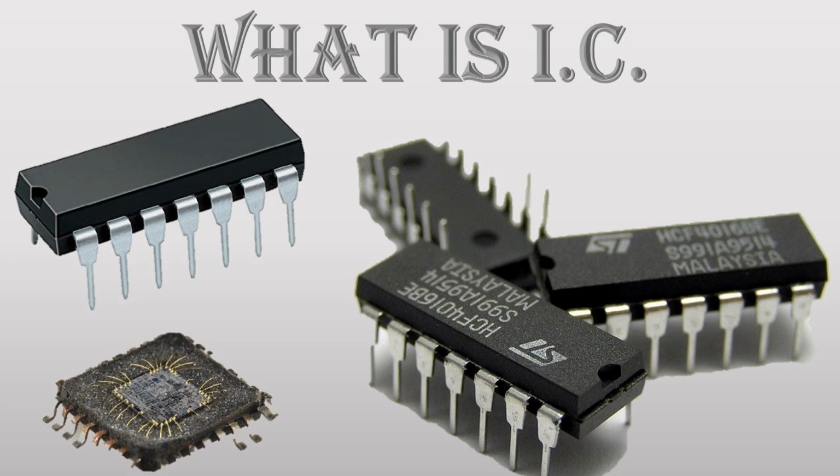XNOR gate, exclusive NOR. Symbol. Operation, outputs 1 if the number of ones in its inputs is even. Otherwise, the output is 0. These logic gates can be combined and connected in various ways to create more complex digital circuits that perform specific functions, such as arithmetic operations, memory storage, and data processing in microprocessors.